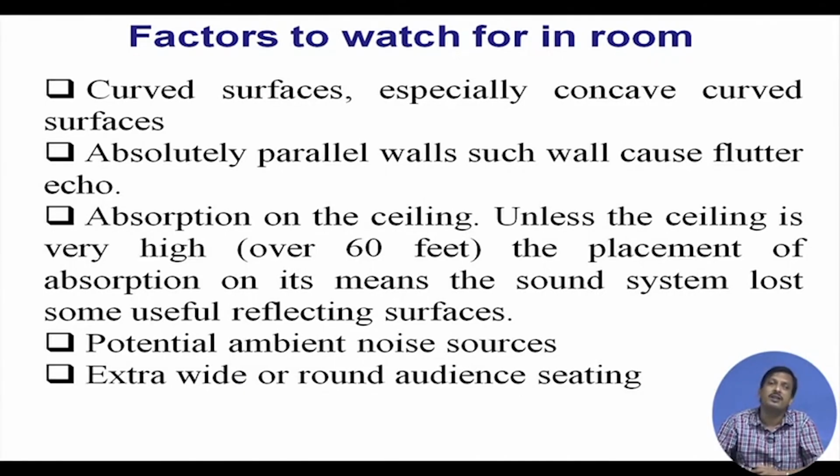What I said, that after the critical distance, the direct sound intensity is less than the reverberant sound, then it creates an effect that the clarity of the speech, clarity of the sound, will be hampered. So, we want the audience to be as close as possible, within some factor of the critical distance.